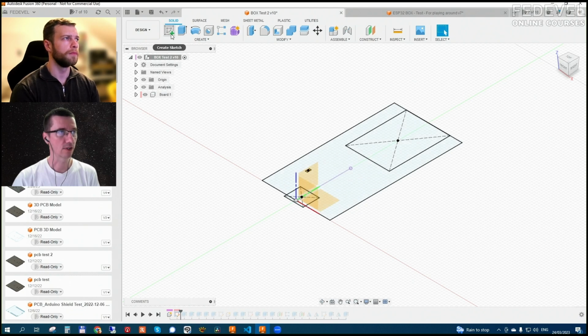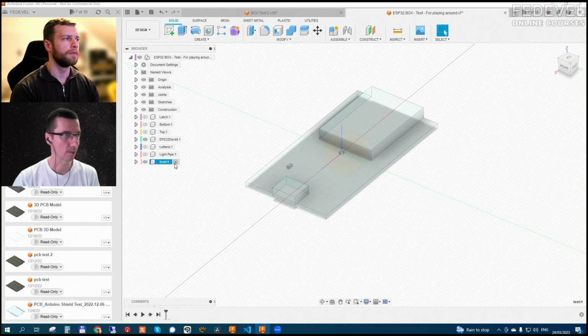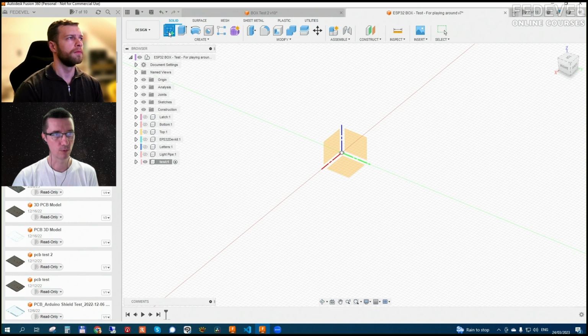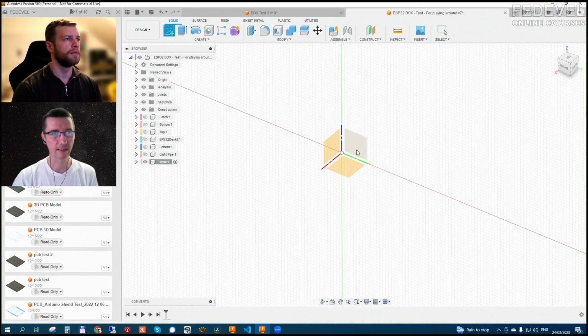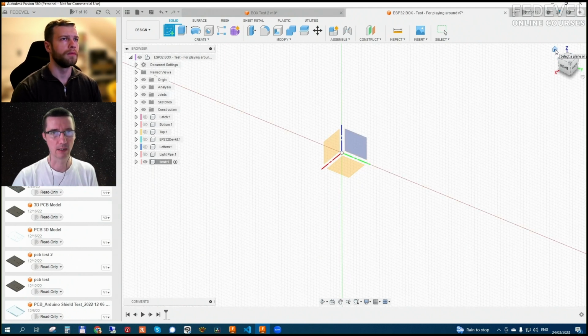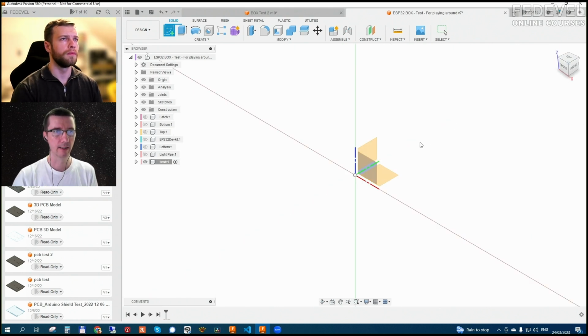Sketch is when you click on this. I go back again here into this temporary component. I can show you what the sketch is doing. I will disable this. So this is active. I'm going to create a sketch. First, you need to select where you would like to draw. Sketch is only two-dimensional. Usually when you click on this home, it will orient the proper way. And when I start, I usually draw on this one, X and Y.